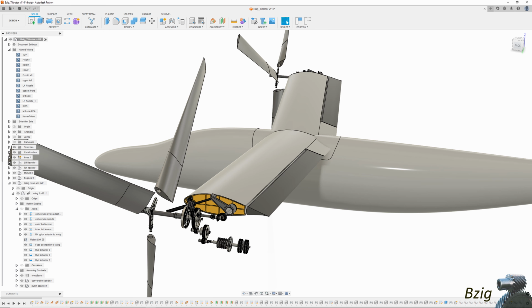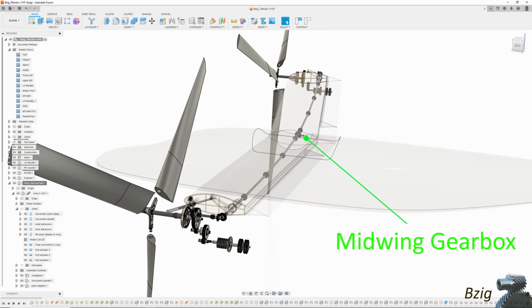The fifth gearbox in this tilt rotor is the mid-wing gearbox. You can see the wing has forward sweep and dihedral. Dihedral is for stability, specifically rolling moment due to side slip, and forward sweep is needed to give the rotor blades adequate clearance from the wing leading edges. This is a swash plate controlled rotor, so the rotor blades flap in order to control the aircraft.